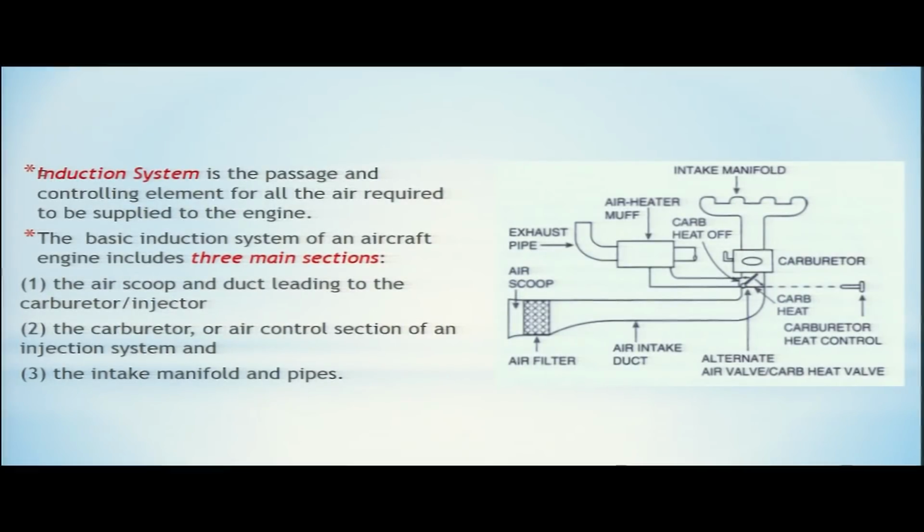The induction system is the passage and controlling element for all the air required to be supplied to the engine. In the diagram you can see there is a duct here, then you have an air filter, and this is an air scoop. So the air enters from this side, it enters the scoop through the filter. This is your complete passage, and it is also a controlling element; it controls the air which is going inside the intake system.